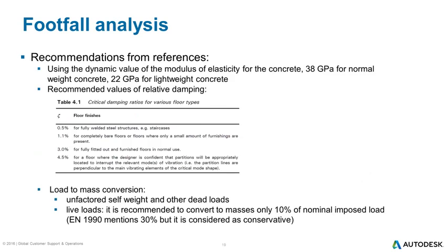Let me show some recommendations related to footfall analysis. It is suggested to set the dynamic value of the modulus of elasticity for the concrete as 38 gigapascals for normal weight concrete and 22 gigapascals for lightweight concrete, rather than the typical Young modulus values, which are different for different concrete grades. For load to mass conversion, it is recommended to use 1.0 coefficient for self-weight and other dead loads, and 0.1 for live loads.